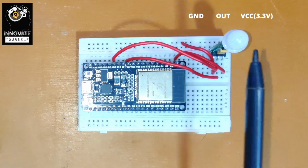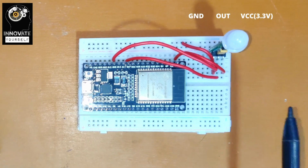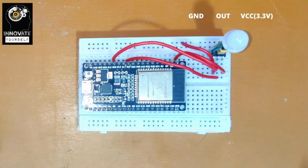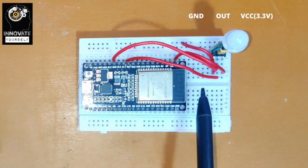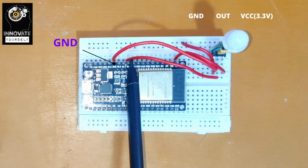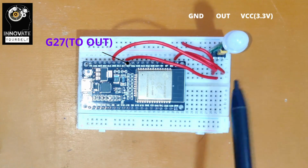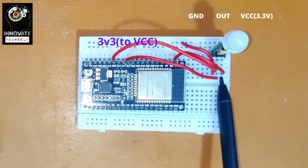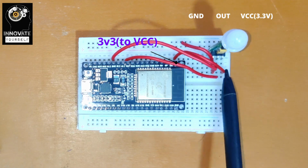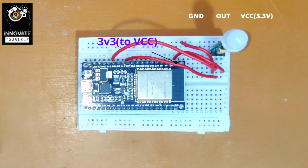So the first one is ground, the second one is your output, and the third one is your VCC, and that VCC will be 3.3 volt. For doing that, the first is ground, and that ground is connected over here, which is this ground pin. Next is your GPIO 27, which is connected to the output of your PIR sensor, and the third one is your 3.3 volt, or you can say VCC, and that is connected to the pin 3V3, which is 3.3 volt, right?